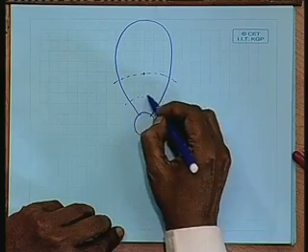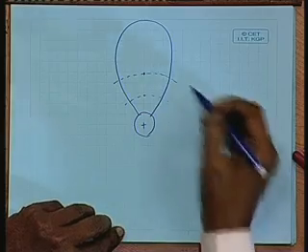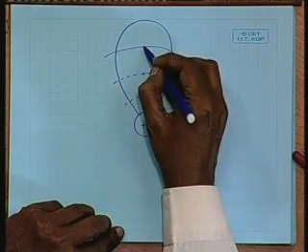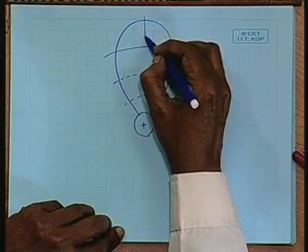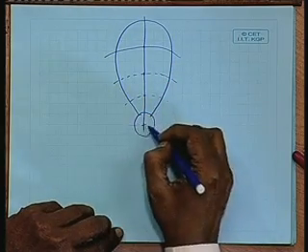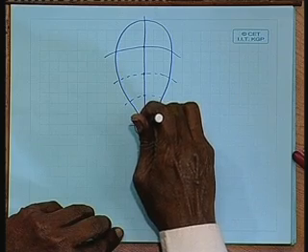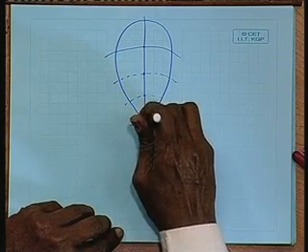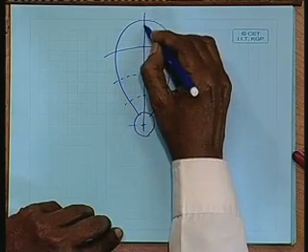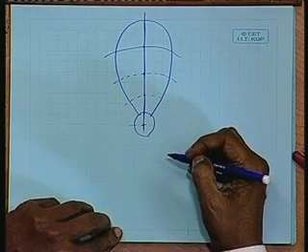If I join the midpoints of all sections like this, all radial sections with this as center, and I find they lie in one line which is perpendicular to the center like this, then this is called a propeller with no skew.